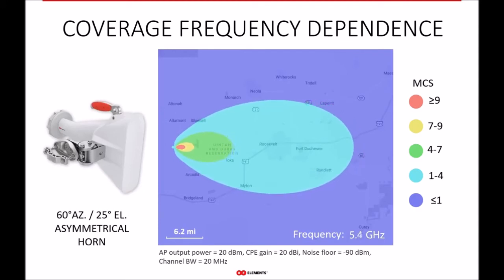Here we show a similar simulation, but for the 60-degree asymmetrical horn. And I will tell you the truth. As soon as you take a symmetrical horn and introduce some sort of asymmetry, meaning you squeeze it and you get the antenna you see on the picture, things will change a little bit. Because of the asymmetry, things will become a little bit less frequency stable, and you can see it on the resulting coverage. It's like a nice avocado shaped pattern, which is again changing a little bit with the frequency, but it's definitely much more stable than anything else out there.